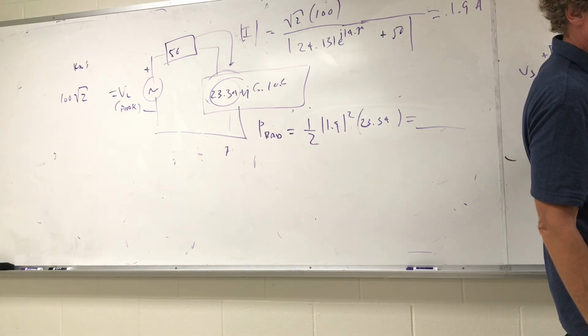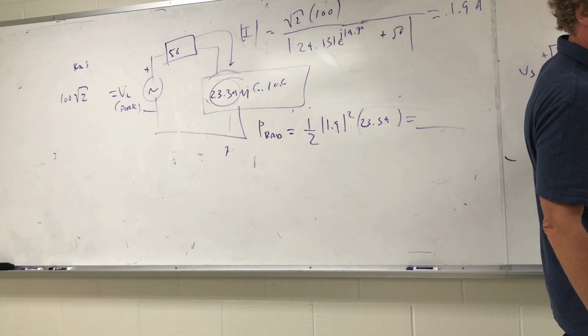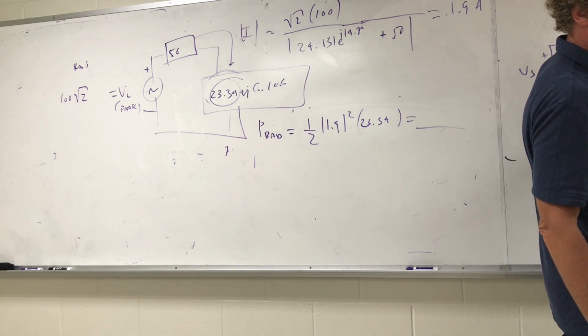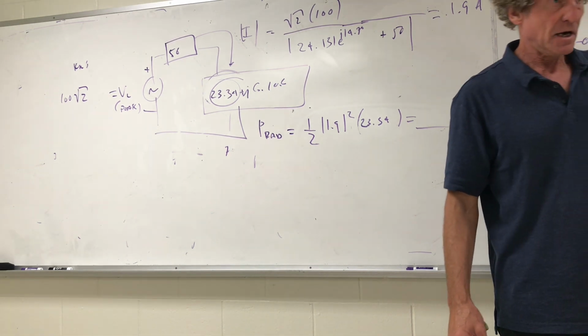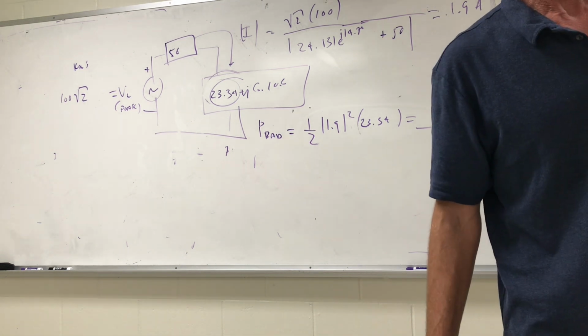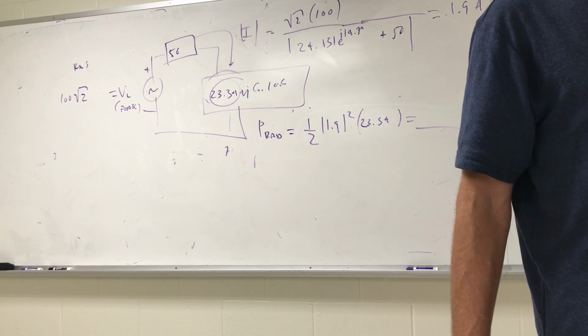A waveguide, remember, waveguides have characteristic impedance, but if you want to match this, then it's basically going to be something where you would have to add, either in series or parallel, just like we do with transmission lines, either an element like a capacitor, inductor, or a stub, shorted, or just like we would. All right, that's for matching.